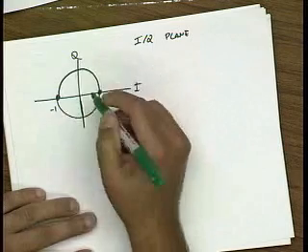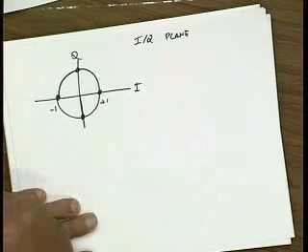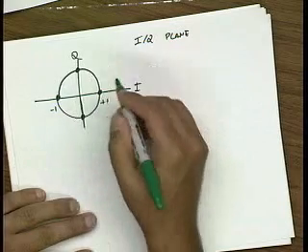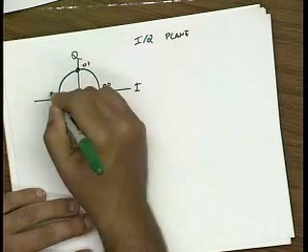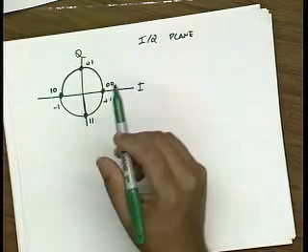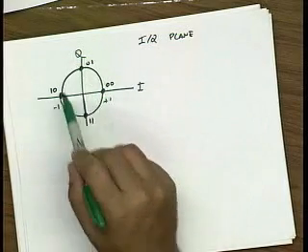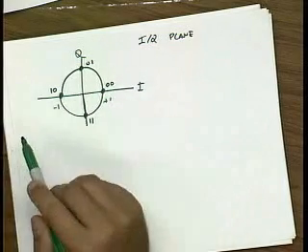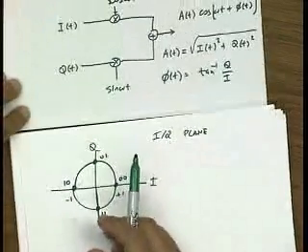If I want to pack more information, I could actually pick 4 points and send these 4 points, basically encode my data. So this might be 0, 0, this might be 0, 1, this might be 1, 0, and this would be 1, 1. So in this way, I could basically group 2 bits together and then transmit one of these IQ signals, and that would represent the modulation. And I can use the simple modulator to do that.